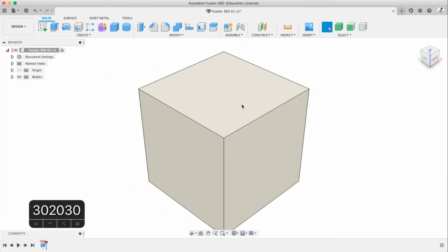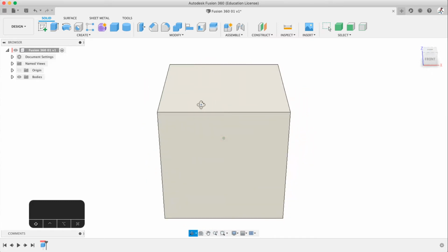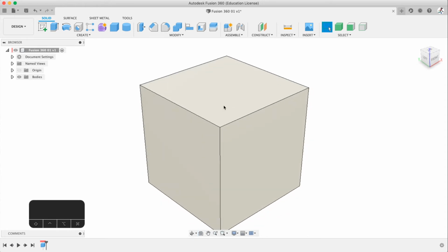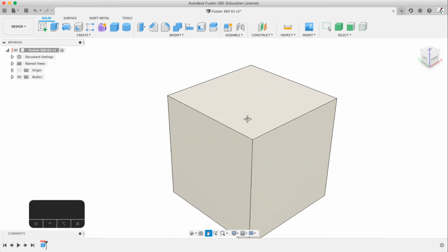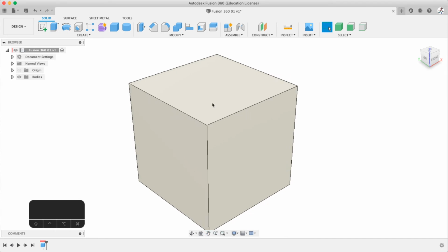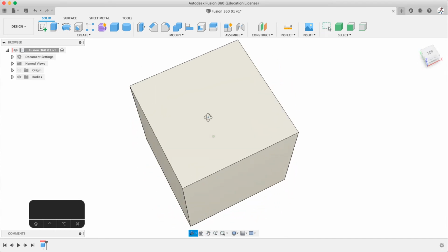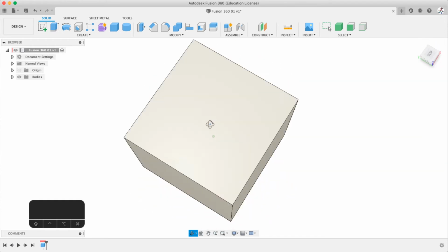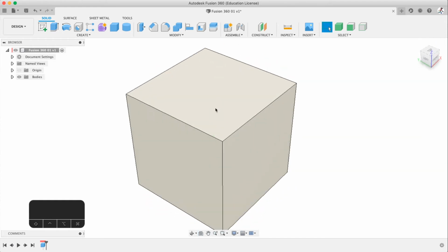Next thing, I want you to hold down the shift button. This is my shift. Hold it down and click the middle mouse button, but hold it. Click it and hold it down, and then move your mouse, and now we're rotating. So we have no shift, click and hold, we drag the camera around; shift and click and drag, same idea, and now we're rotating. So that is how we navigate around.